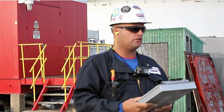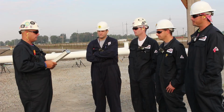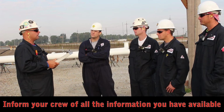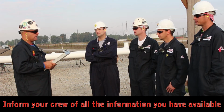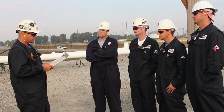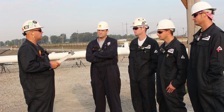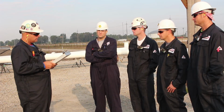In our permit package, we have a Hot Works permit. We got to be locked out. Everybody locked out on lockbox 39? Yes. Okay. We do have a permit for a crane lift, and we are going to be entering a confined space. There's a fresh air checklist in there, and there's a variance in there for blinding. And there's an ERP that is written, that is in there, that is current and up to date, that I just checked. I walked the job down this morning. Everything appears to be in good order. We will all go over it right at the job site before we start work, okay?